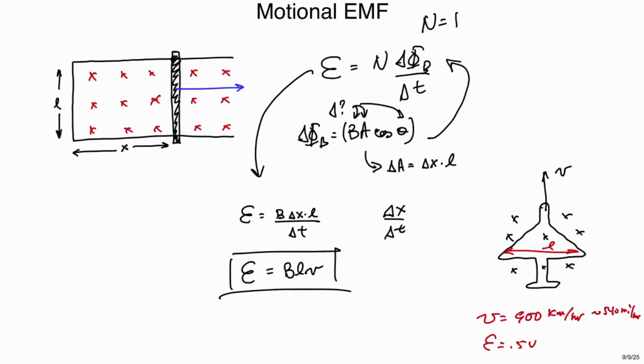That coil of wire is talking to another coil in the charging pad. The one in the pad switches its current back and forth, it'll communicate that to the next coil via Faraday's law of electromagnetic induction, and you'll have your phone being charged by induction. Those are inductive chargers. This was an inductive thing.